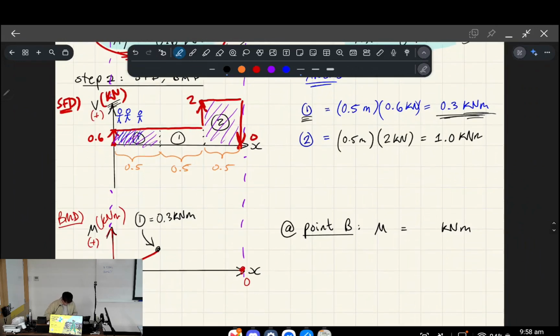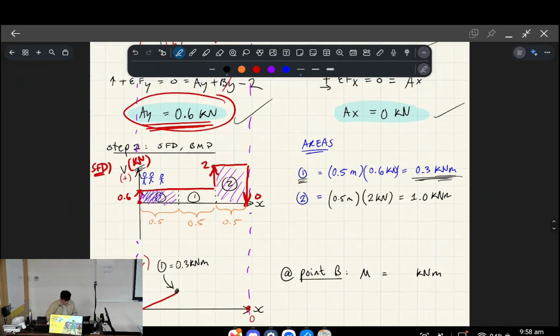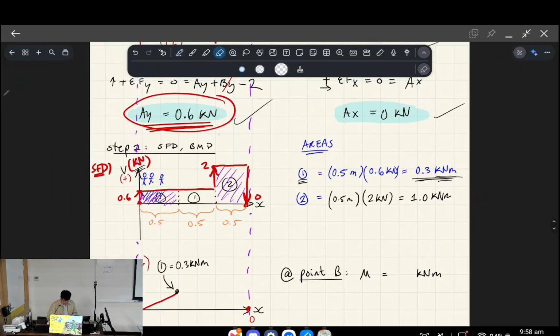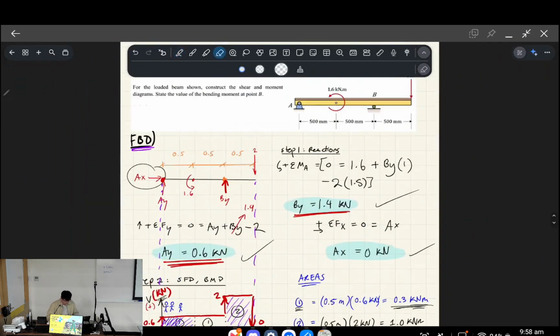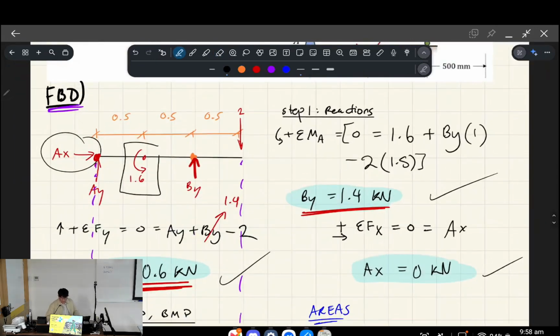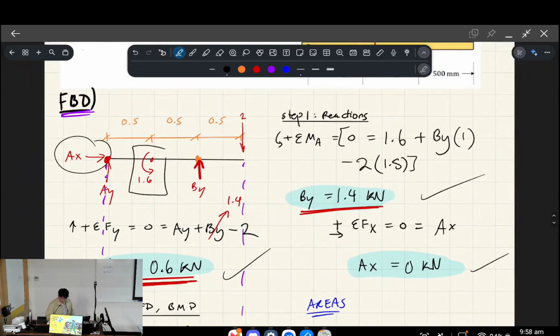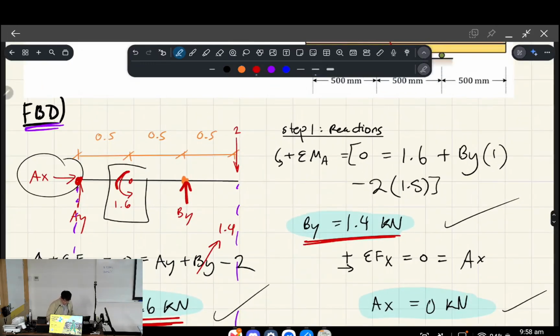Now, what's probably not going to be super intuitive until you see this done with the algebraic method is that now when we look at this point moment, right, which we have to consider now that we're looking at the bending moments, the internal bending moments, is that we know that this is a counterclockwise spin. So counterclockwise to us, right, intuitively implies that it's positive, right?